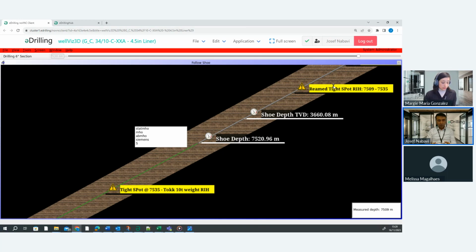The other part, which is very important, is rheology, which of course affects a lot during drilling. It's changing all the time. We have 2 options. You can insert the rheology manually. That's one option, but not the best option. The other option is that you have some sensors on the rig side which measure the rheology, and then the system takes the real-time rheology all the time and uses that for the simulation.